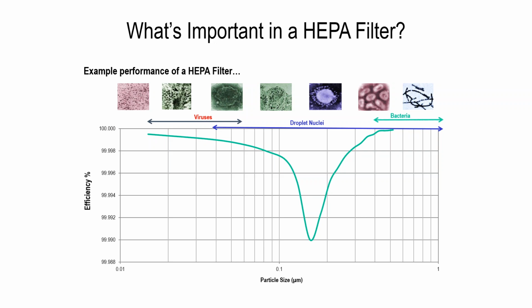That's the particle size that we're most preoccupied with when it comes to the filter. What you'll also see is that the efficiency starts to climb again after we pass that MPPS rating, and it begins to skyrocket as the asymptote approaches back to 100%. And the reason for that is the diffusion principle that I mentioned a couple slides ago, where as the particles become smaller, there's random molecular motion, and as a result of that, it runs into the media, which increases the efficiency of the filter again.